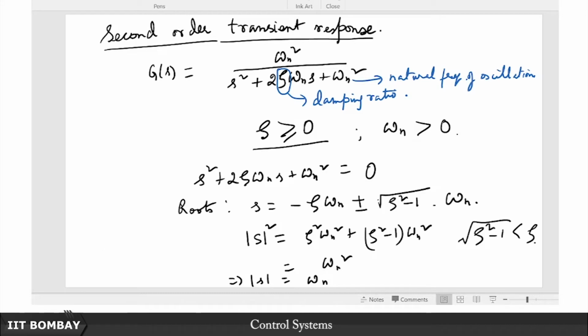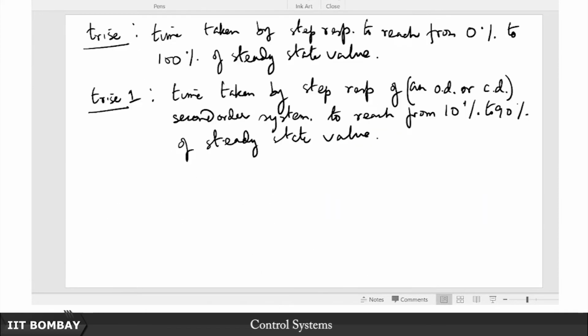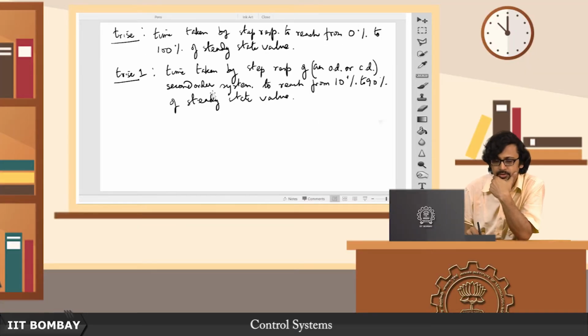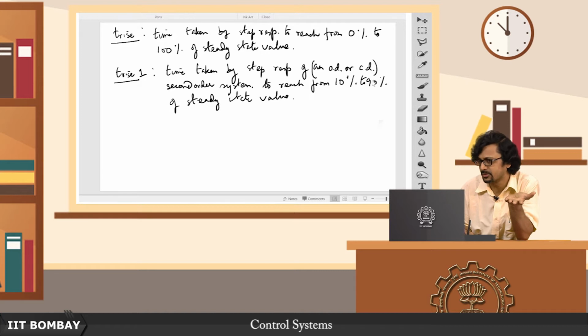So in other words, what we are now saying is, in view of this new revelation, the larger the magnitude of your roots of the second order system, the smaller is the rise time, that is the sooner the system rises in response to the application of a step input. Now of course you might say, you define this rise time in two different ways, what about the second way? The second way, as I said, is more applicable for the overdamped and critically damped system, because of course they never really attain the 100% value until t is infinite.